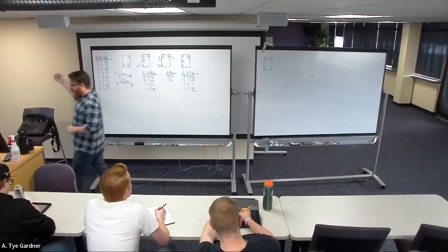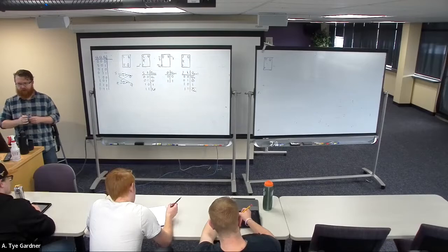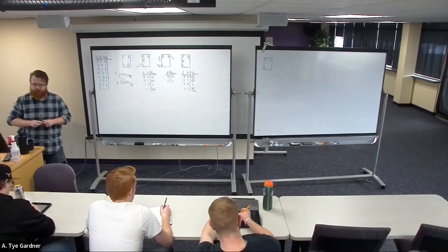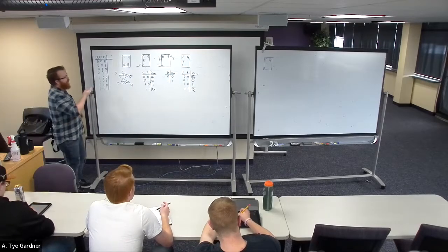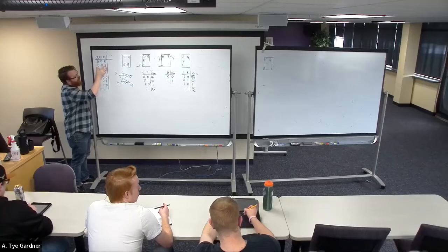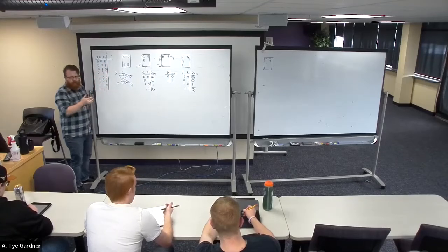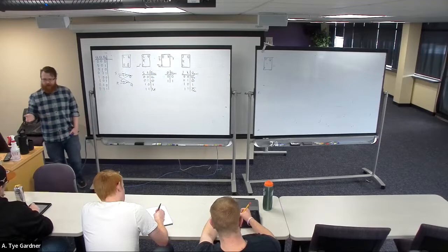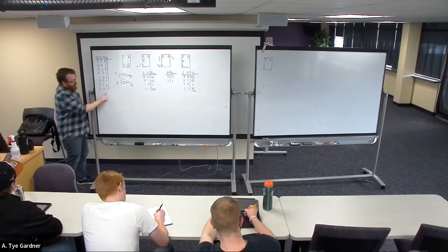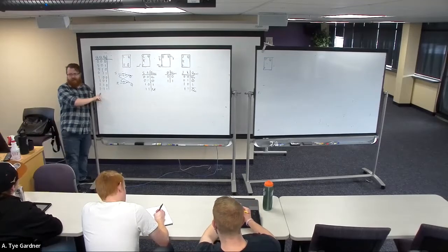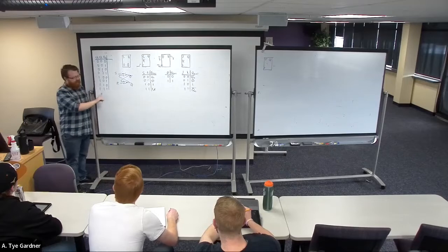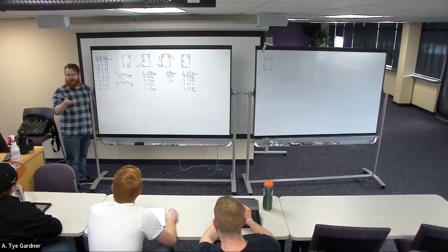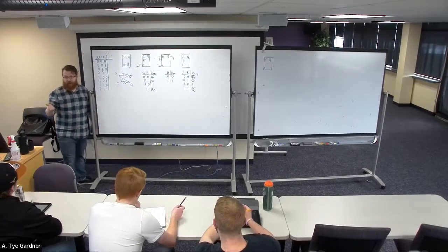Now, these turn out to be incredibly useful because if we look at the number sequence, right? Even before I taught you guys how to count in binary, I taught you truth tables, right? And we can build them with a pattern, which says we want to go 0, 1, 0, 1, 0, 1, 0, 1. And then the second one is 0, 0, 1, 1, 0, 0, 1, 1. Which in a way is saying that if in each column I could have a clock that is running half as slow as the previous column, I would be able to build what's called a counter, right?